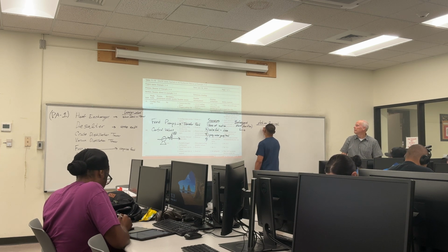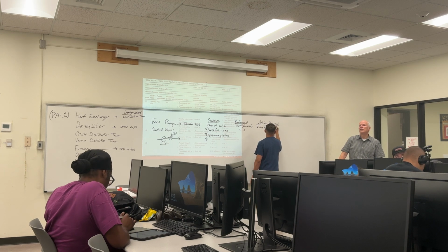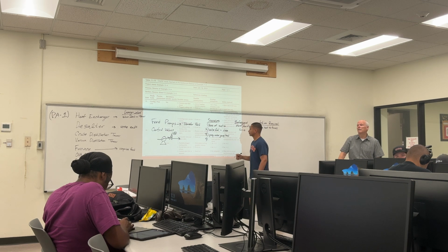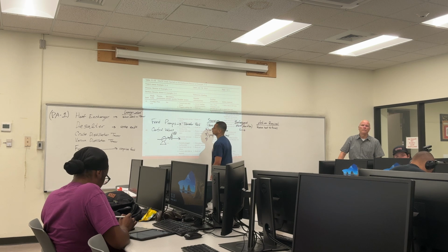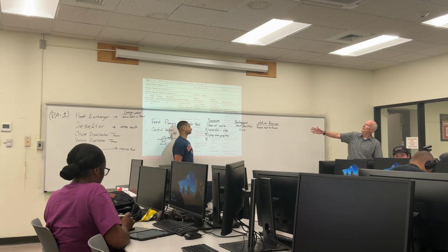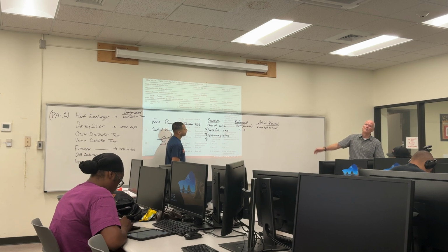What was our action required? Reduce heat to the furnace? I think that's what it was. Shut down the furnace. Cut off that flow. Or if you lost flow already, you've got to figure that out. You can't get it back immediately. Okay. Whoever's in charge of safety, do this for some of your more interesting and important equipment.